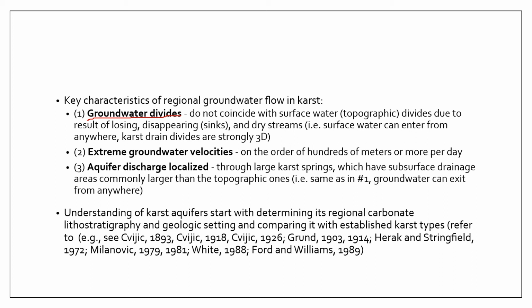They just typically follow the topography. But in the case of karstic aquifers, most of the subsurface water flow paths will not coincide with your surface water or your topographic divides.